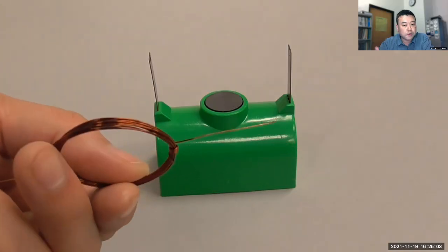If it's stripped off perfectly uniformly, then the motor shouldn't work, technically, because the net torque over a whole rotation adds up to zero. Now, in experiment, it turns out not to really work out that way. Even if you strip it all the way around, it still works. I imagine because the electrical connection we make is such a poor connection that as the thing turns, there's enough asymmetry that it still works.